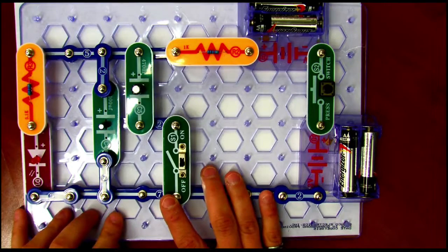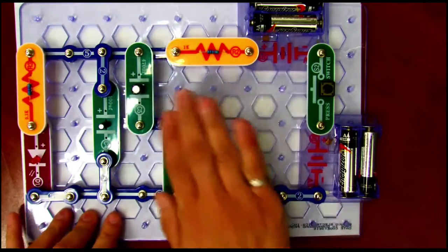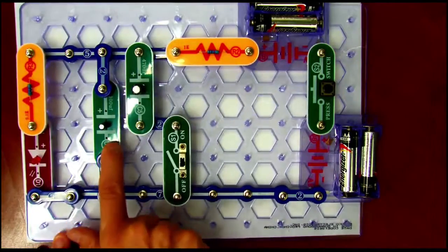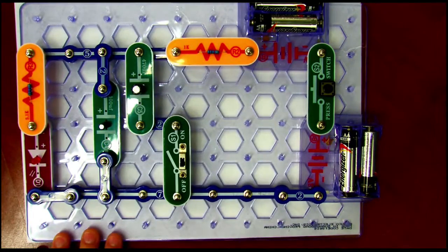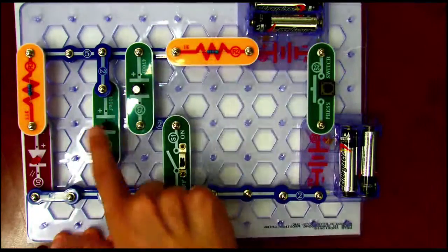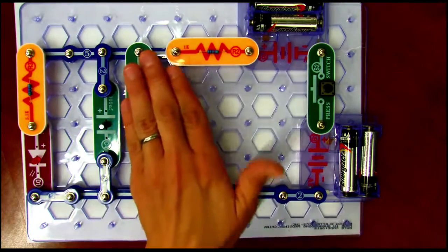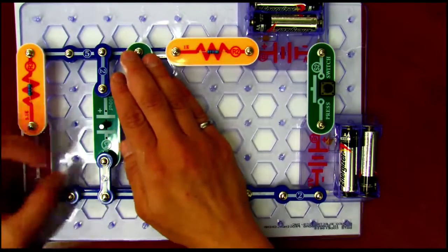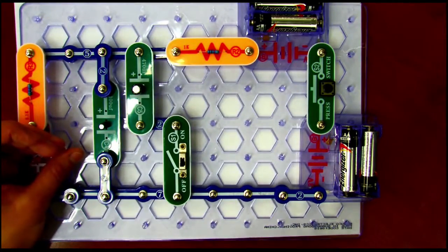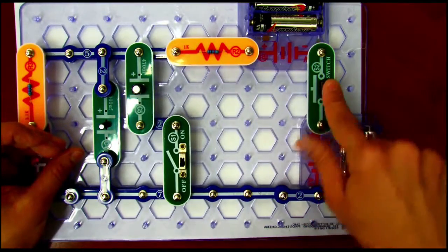So right now, this switch is off, and this is a 470 microfarad capacitor, so he's not in the circuit. What is in the circuit is this 100 microfarad capacitor, an LED, and some batteries. If I press this switch, I'm storing energy in that capacitor, which can go to the light bulb. This guy is off. He's out of the circuit right now. So we're going to block him off. I'm going to pretend he's not here because I need to put my hand around this light. So right now we're just going to use the 100 microfarad capacitor. I'm going to press the switch.